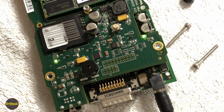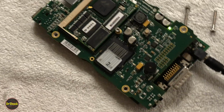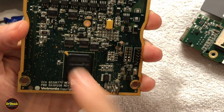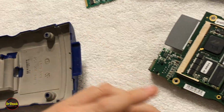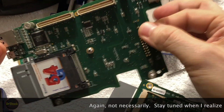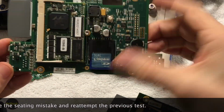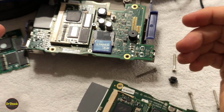Well, there you go. This one's now ready to put back in service. So in this case, this FPGA is also bad on this original MDI, and we've just confirmed that by swapping it from the other one. However, on the other one, we know it's not the daughter board, so it's got to be this board. So this board is bad. Something on this board is shot that is causing a problem. So this at least is a way you can narrow down of the 3 boards that are involved.